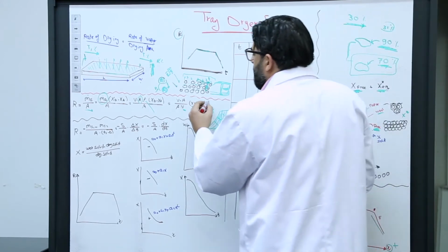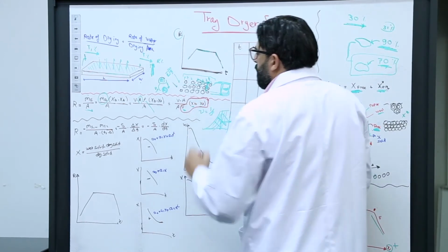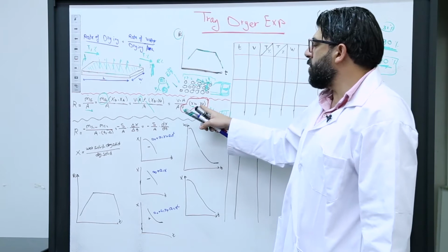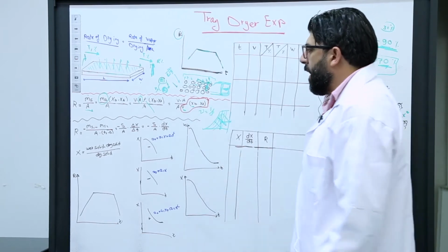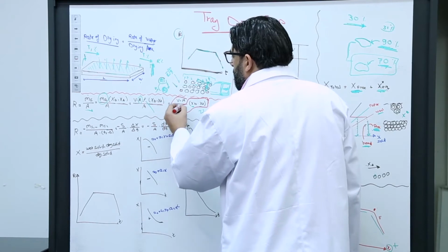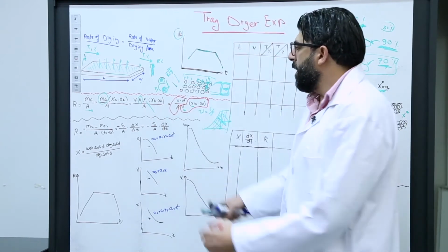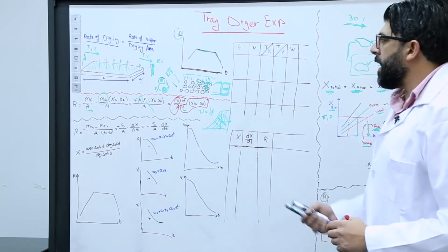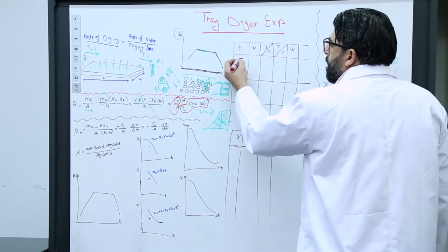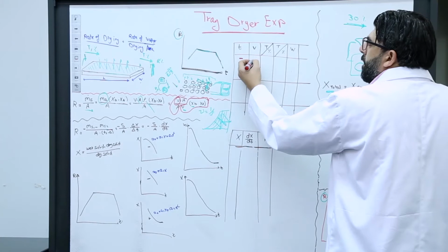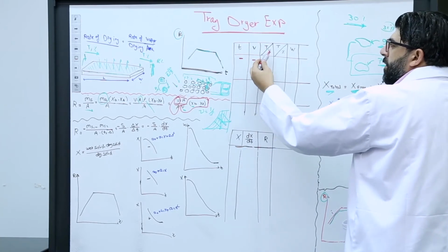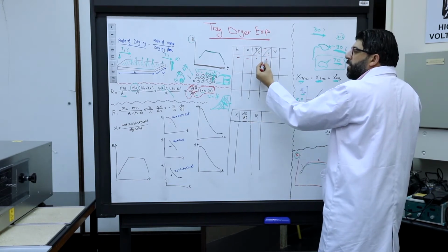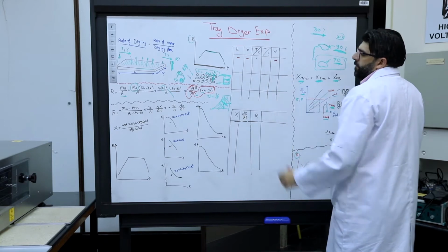All these properties can be found from the psychrometric chart: specific volume, absolute humidity at the exit, absolute humidity at the input. The other properties, A and A, are given from the lab manual, and V is given from the raw data. In the raw data given, you have a time, you have velocity, you have temperature and relative humidity pre the trials, temperature and relative humidity post the trials, and you have the weight. Okay?